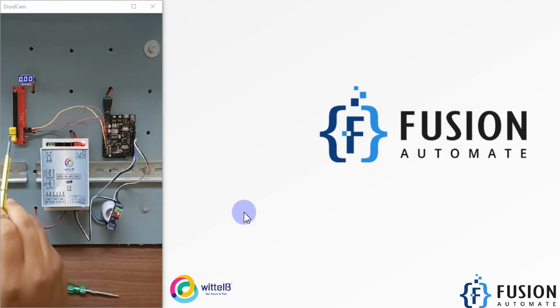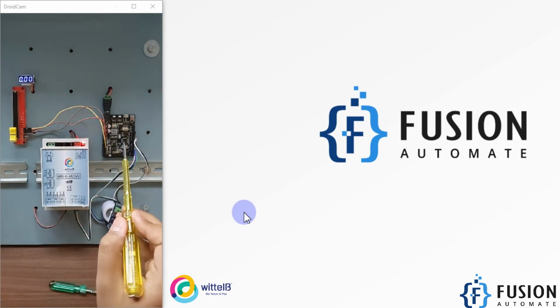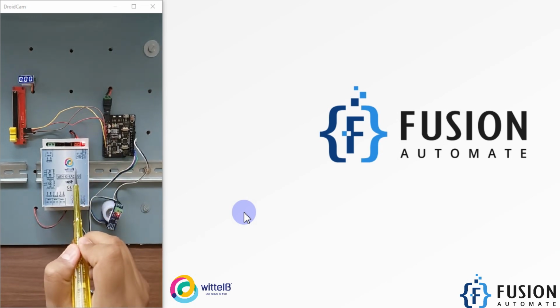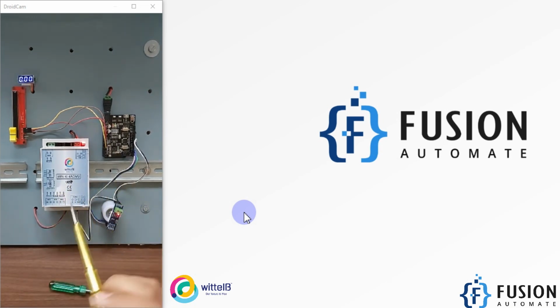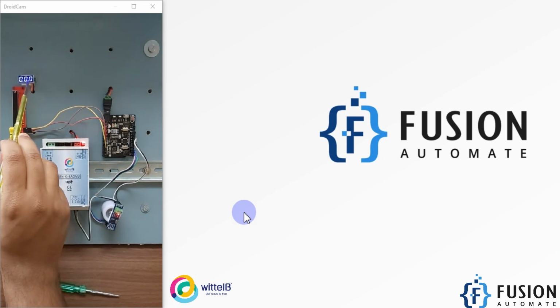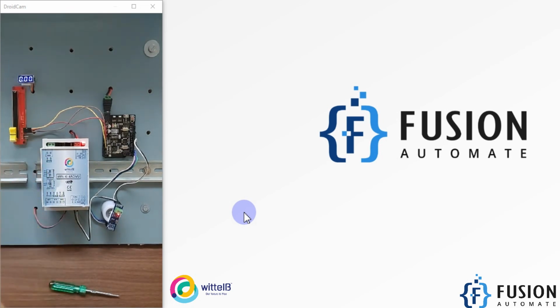Whatever reference I provide from my potentiometer will come to Arduino, and Arduino will pass that value to this Modbus IO card. Based on that reference, the card will set the analog output voltage levels, and you can verify the analog output voltage reading on this DC voltmeter. If I change the set point now, you can see the analog output voltage is changing. If I change more, it is not properly linear.